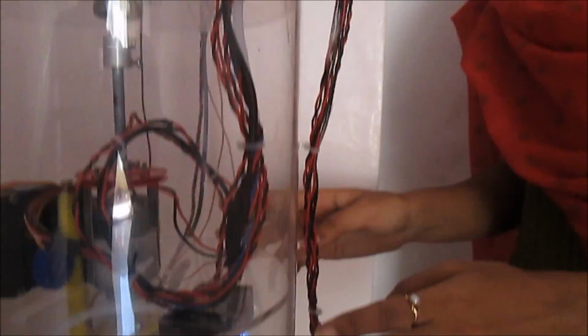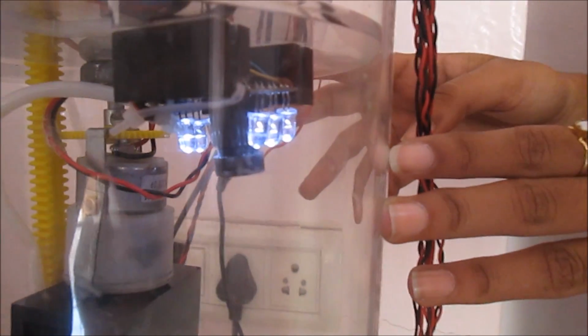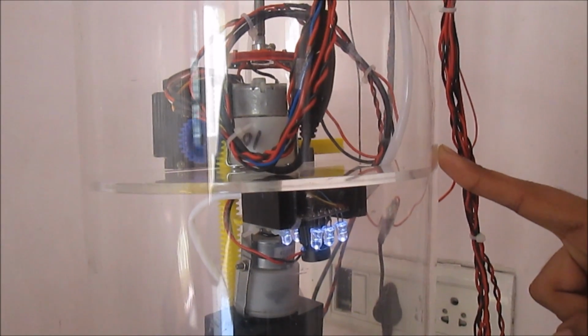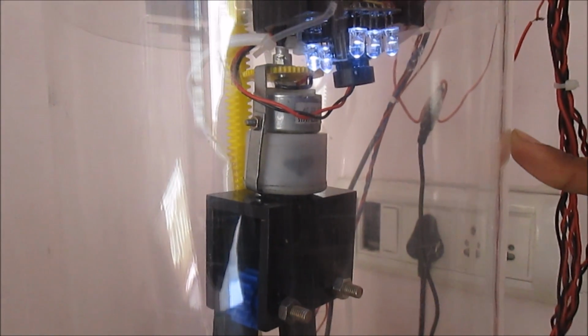For the implementation, we have mainly used 4 DC motors and 2 servo motors. One DC motor for the pulley system, one for the rotation of the disc having a camera attached, one for the rotation of the robotic arms, and another for the opening and closing of the robotic arms. All the DC motors have 3 kg torque and the operating voltage is 12 volts.